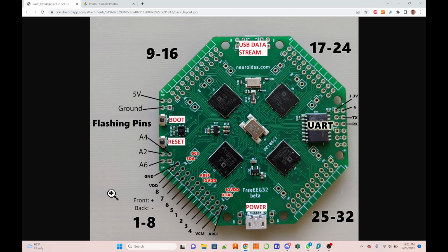Okay. So in OpenBCI you have the bias pin, which is on one of the ear clips, and the bias is basically a way of connecting in a stable way the voltage potential of the board with the voltage potential of the body, such that they have a stable reference to each other, and then from there you measure all the other positions.